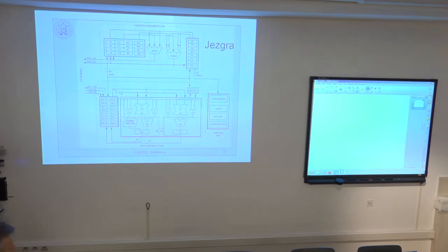It is the same as with this simple architecture. The arguments cannot come directly from the memory. So they must be prefetched into these registers with a fetch instruction. And once these are here, I can use them as arguments for multiplication or ALU operations. The ALU is also implemented here. It is not shown because it is much simpler than the multiplier.